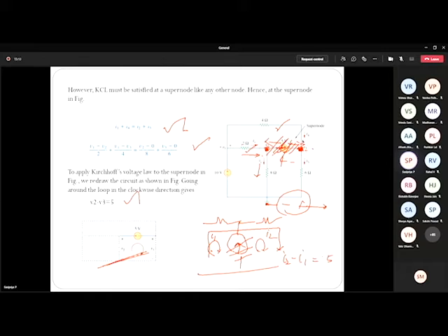That's why I said, normally the practice is to assume all the currents through the resistors as leaving currents, because then you will get the common conductance as the negative element. But here, since we are going to write the equation directly, let us not worry about it. So here, this is assumed like this. As far as this node is concerned, one is entering current and the other is leaving current, that is I1, I2.